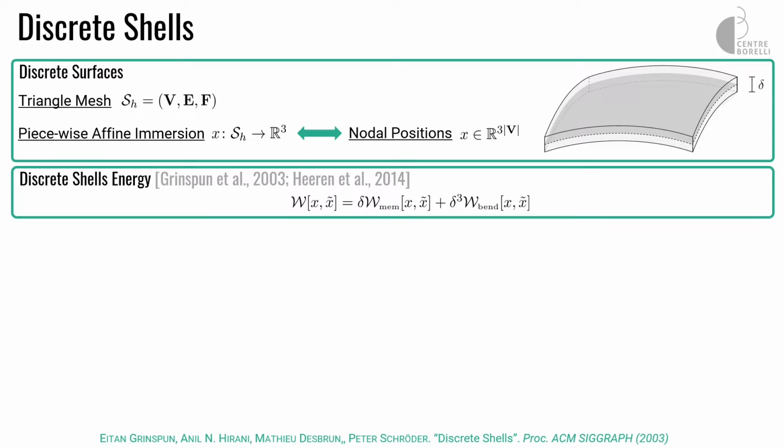Intuitive explanation. Okay, so the true explanation is that these are different. To get these kinds of models, for example, to get the bending model, you would assume that it's basically isometric deformations. Then you look at thin 3D objects, and you can talk about limits of having the thickness go to zero, and look at the gamma limits of three-dimensional elastic energies. And in the right scaling regimes, either membrane or bending energy pops up.